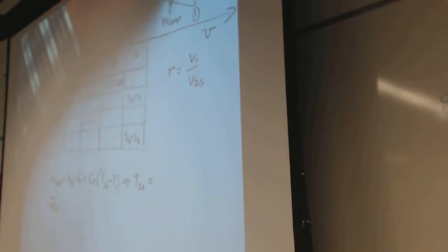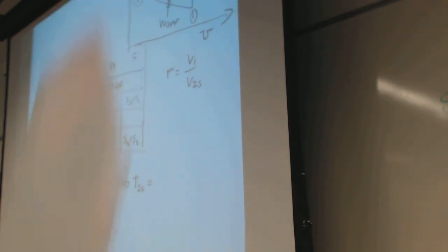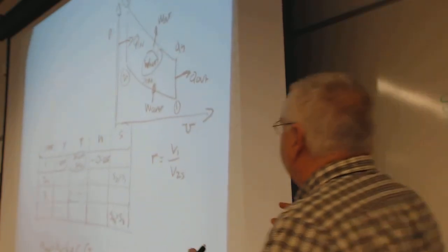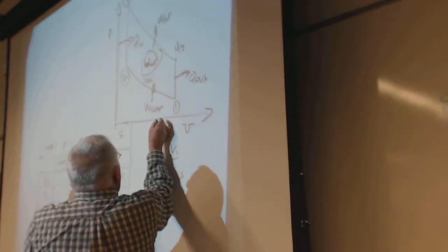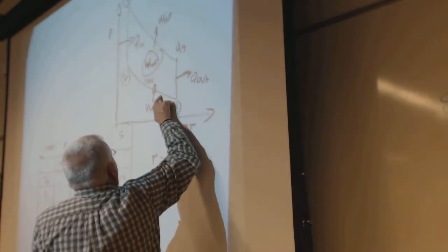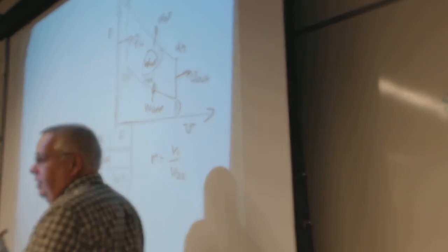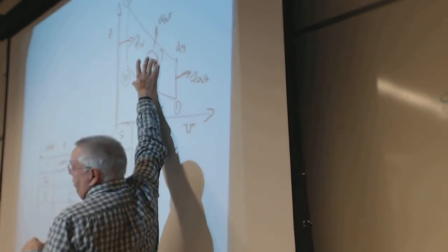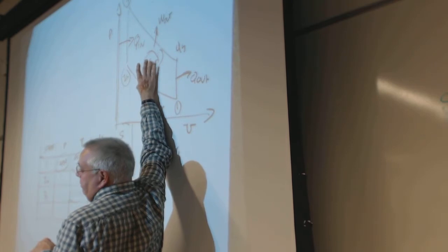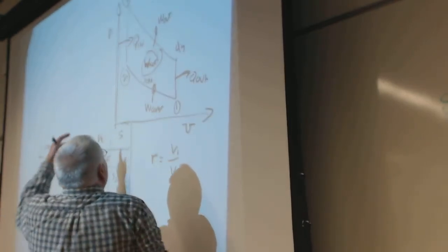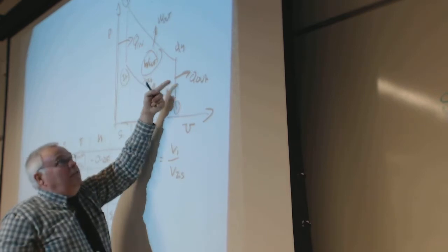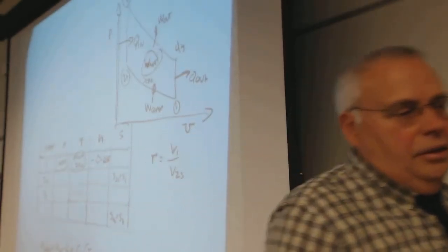conceptually in this diagram, the pressure times the change in volume is the work that's being done. The work under here is the work that went into the compressor. The work at the top is the work that came out from the piston pushing. And the difference between the two of them is how much you get to take out to the shaft, conceptually. The heat that was in is what drove it. The heat out was our exhaust.